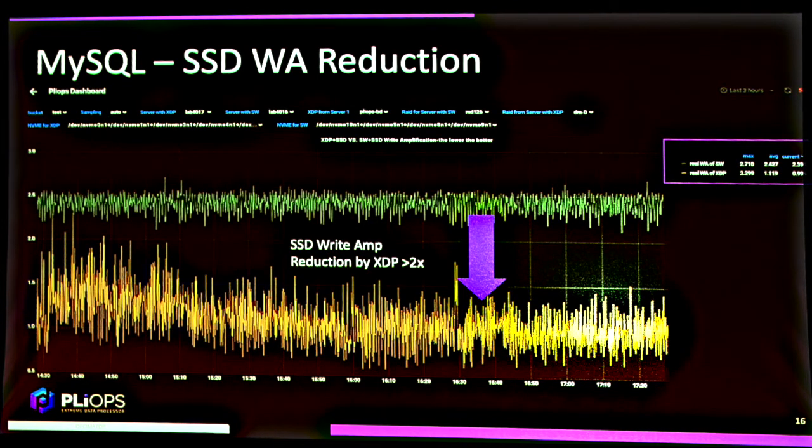The dollar per terabyte on a TLC SSD is $132, and on a QLC it is $98. So there is a flat $32 per terabyte savings, and you multiply by 40 terabytes per server, multiplied by 30,000 servers they have. So the total, just from reducing this write amplification, the savings is around 7 million.